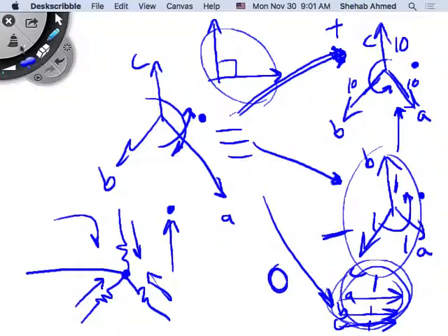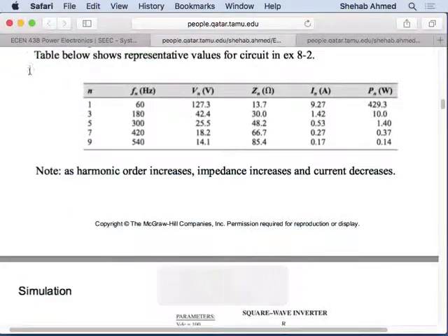Okay? Why are we talking about all this? Because the third harmonic, again, that's in 459. We'll talk more about that. But the third harmonic is a negative sequence as seen by a motor, right? Sorry, the third harmonic is a zero sequence. Fifth harmonic is a negative sequence. So if you have power in the negative sequence, power in the zero sequence, then what are you doing? You're going to be breaking your motor, heating your motor, not contributing to torque production.